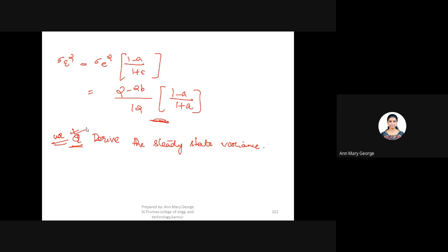Next topic is the product quantization error. What will be the product of 2b bits? When we take the product of numbers with b bits, the product usually consists of 2b number of bits.